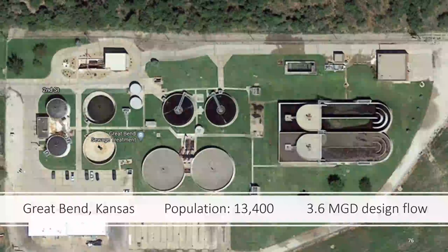But now there's a lot of plants. There's a plant in Tennessee that runs 3 hours on, 3 hours off. There's plants that run more than 3 hours on and off per cycle. SBR is the same way. So I think you've got a lot of flexibility. You could probably go as much as 6 hours in this plant. Most plants could not. That's way too long. But I like to see, for most plants, an hour and a half off for the nitrate removal. That's typically a good number to get that nitrate to drop down, or the ORP to become anoxic enough, get down to that minus 100.